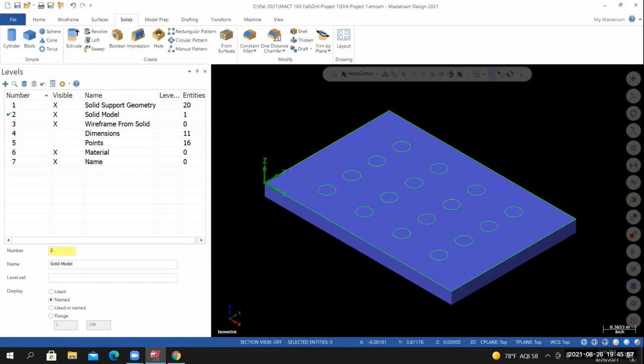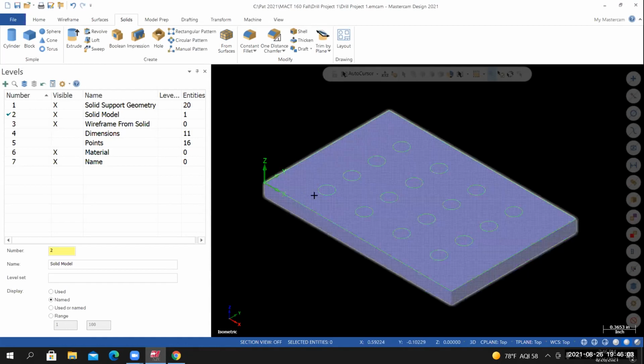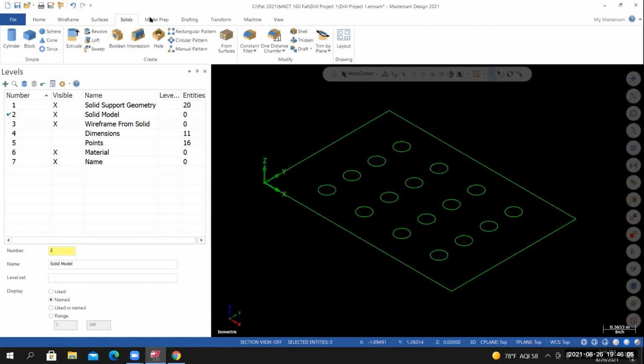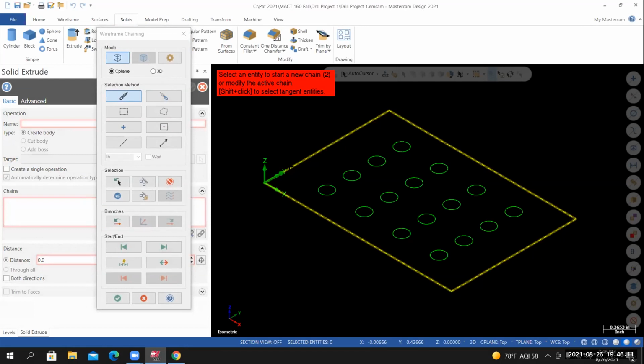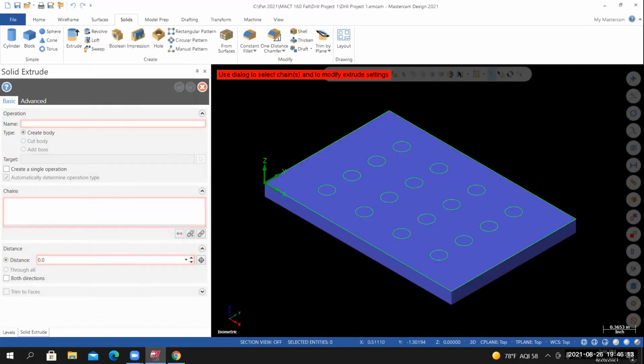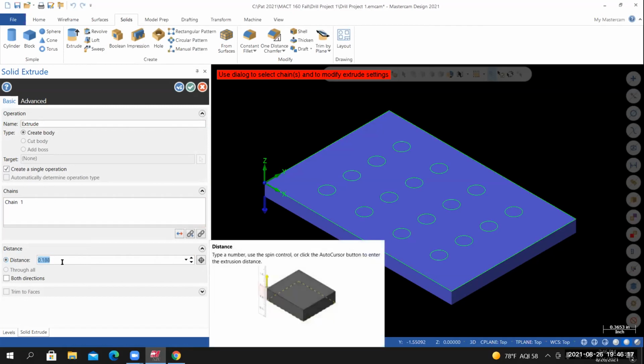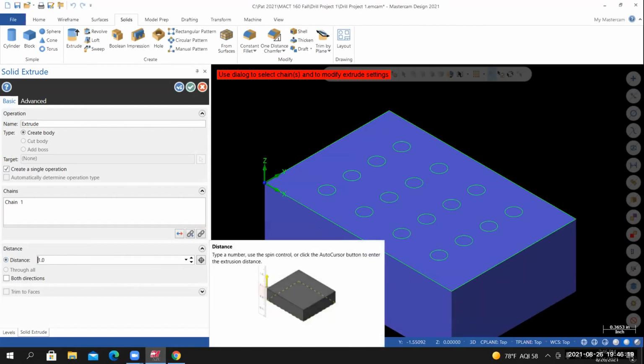Okay. Can you go over changing the thickness again? How did you change the dimension? How did I change it? No problem. Let me delete that. So if I go to solids, extrude, select the outside edge, everything becomes selected. I'll select OK. For the thickness, the default length or distance is 1 inch. This is what you're seeing right there.